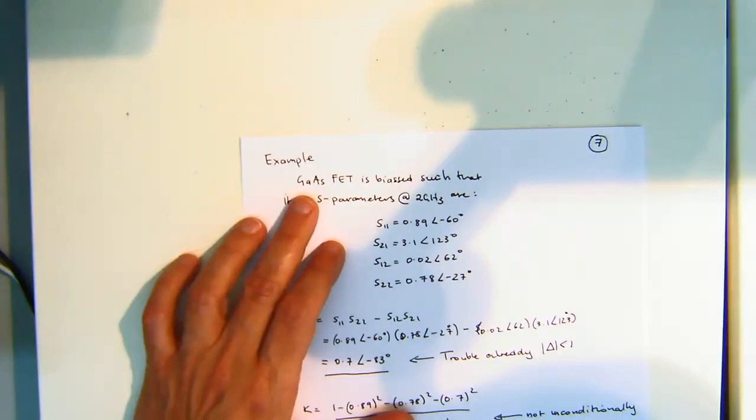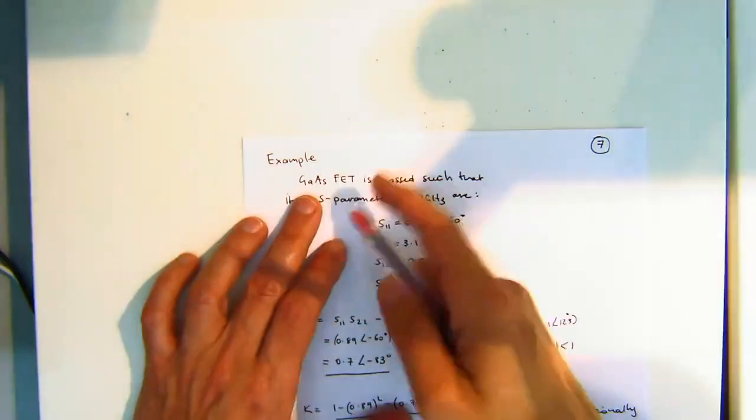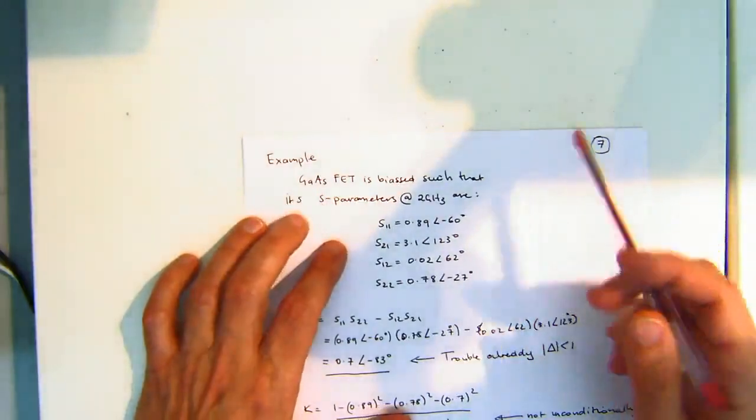It's great for making things for radars or high power communication systems. But the transistors are usually larger and they also consume more power. And you also don't have complementary pairs like you do in CMOS. You don't have the enhancement and depletion or N and P type devices to be able to make complementary pairs, so it's almost like designing with an NMOS.